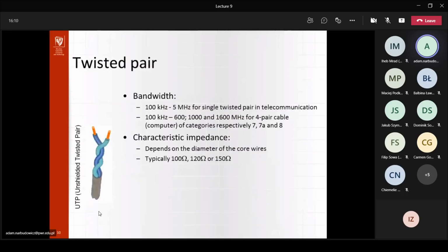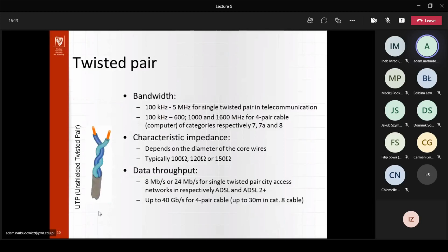Okay, so this is just a brief mention of the most simple case. So we have a twisted pair of two cables, and basically, as the name says, it's two cables wrapped around each other. One carries the positive charge, the other the negative charge, and basically the electric field builds between the two cables. However, in this context, what's important is that the two cables are not really bounded by any metallic conductor, right?